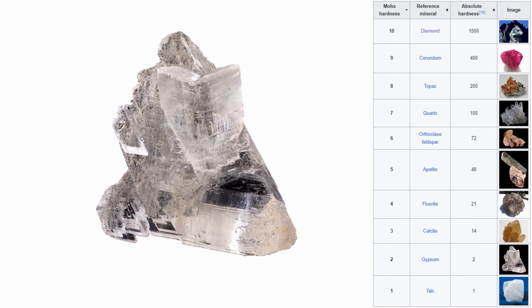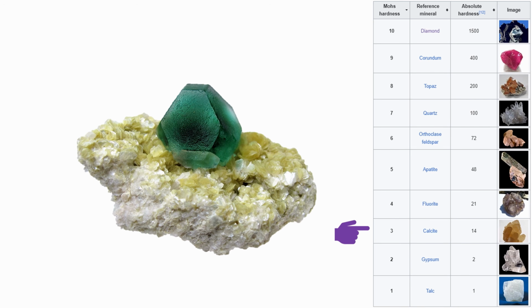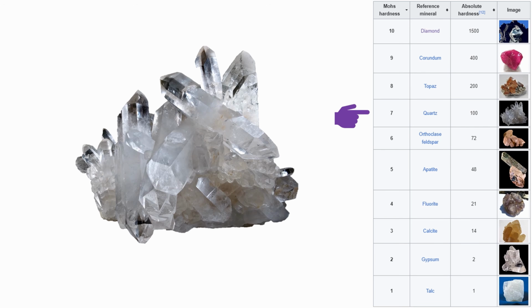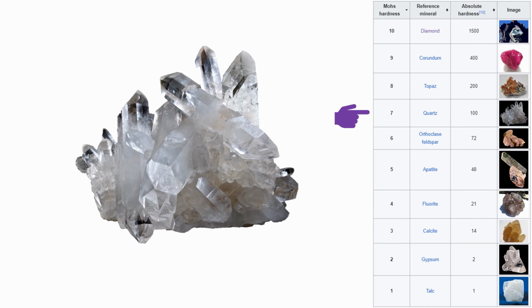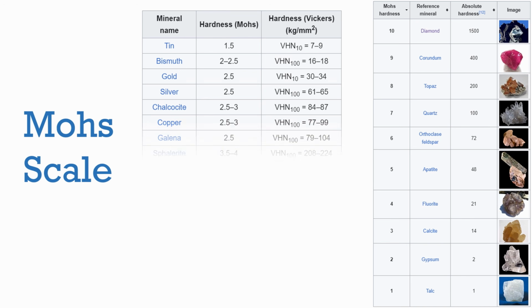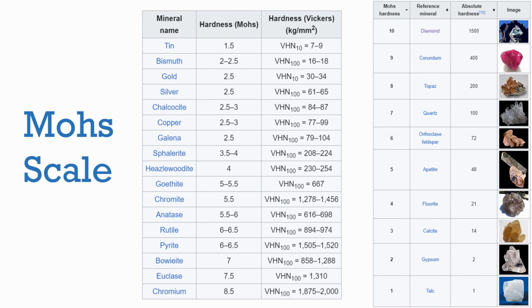And the process of hardness testing is quite simple. We start by trying to scratch with the mineral which has the lowest hardness as per rough estimation, and then we go up one by one. The first mineral which successfully scratches the component is considered the hardness of that component material. And also there is a conversion table for this scratch hardness into the Vickers hardness scale. The Vickers hardness scale is the widest scale among all the hardness scales. We will get to it later in this video.